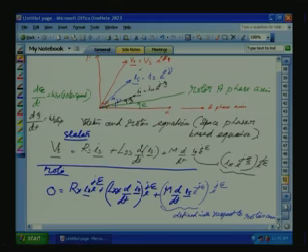Now multiplying by e raised to j epsilon, this will bring the rotor voltage also along the stator axis. That means the common reference axis. So now we have the stator as well as the rotor voltage terms with respect to a common reference axis. So now if we split into ABC or alpha beta axis components, you will get the dynamic equations for the stator and the rotor.